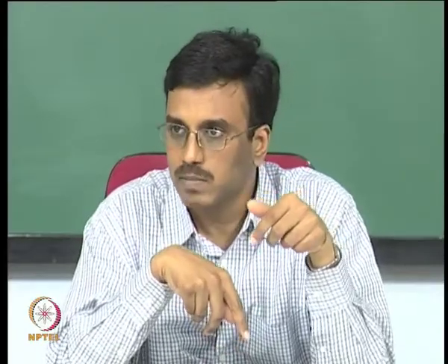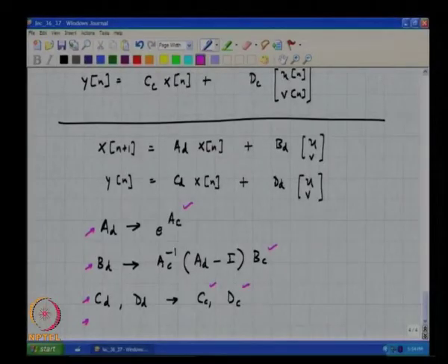Using this formulation, can one put a sinusoid at Fs? Ideally, if you take a real continuous time sigma delta modulator and put in a sinusoid at Fs, what should the output sequence be? It should be 0, correct.